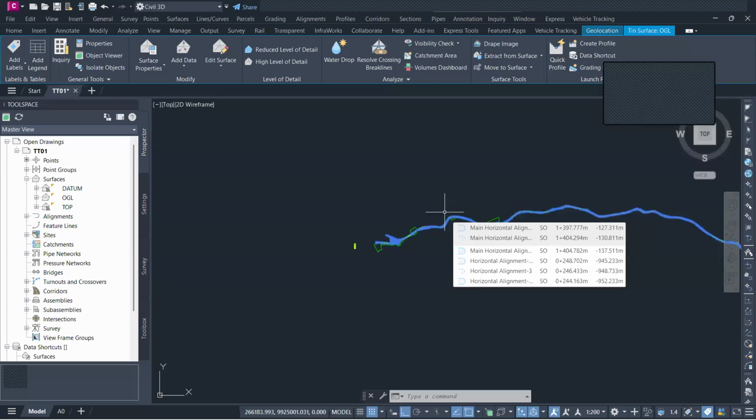And then once you have that 30 meters, you are going to multiply it with the length of the entire section. So let's say, for example, this one is 10 kilometers. So it will be 10 times 1,000. Then you're going to divide this with 10,000. So site clearance is again paid in hectares. So you convert the square meters into hectares for that matter.